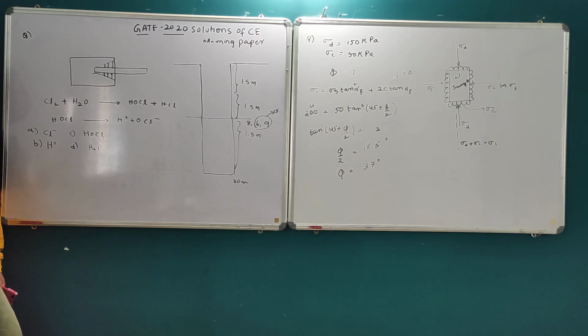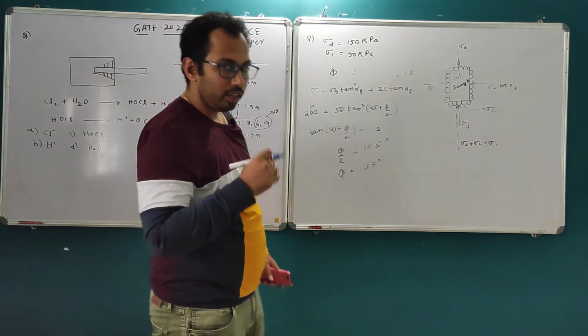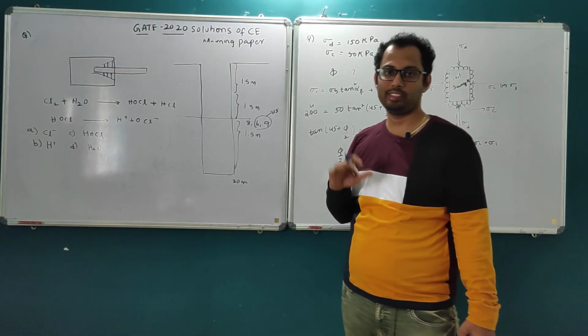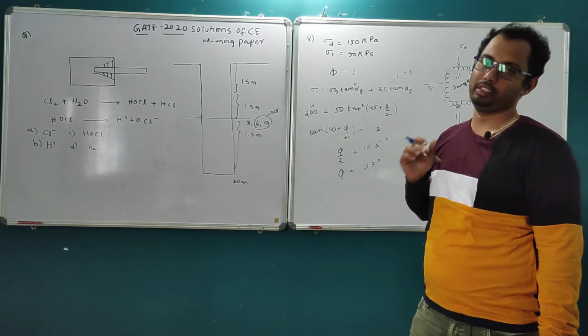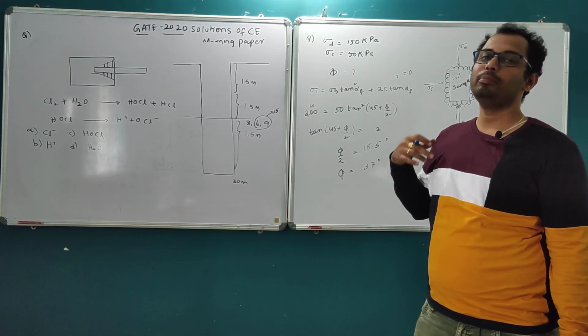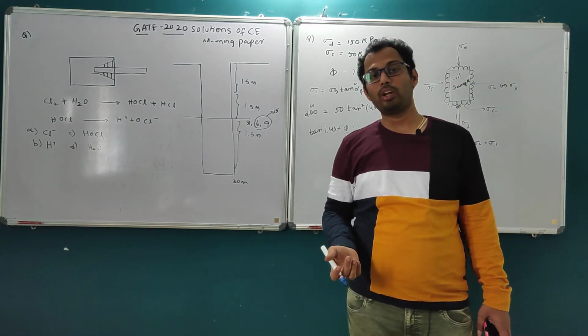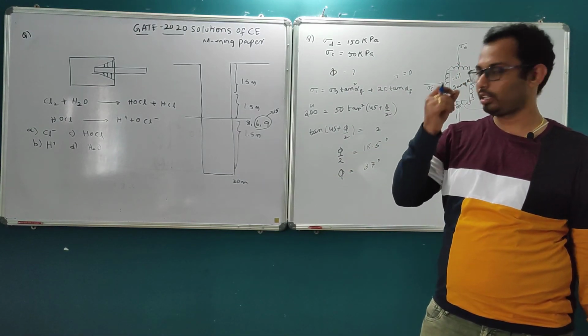But here chlorine was given with a charge. It is an anion now. It is no more stable matter. It is active matter because of negative charge. So first it will think, forget about disinfection. What it will think? First it needs to get neutralized. So the Cl minus will search for a cation rather than disinfection first. Once it meets the cation, it gives the electron to the cation, then it will stabilize itself and then it will start disinfecting.